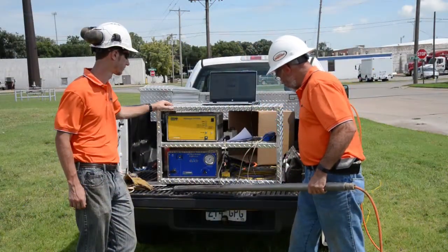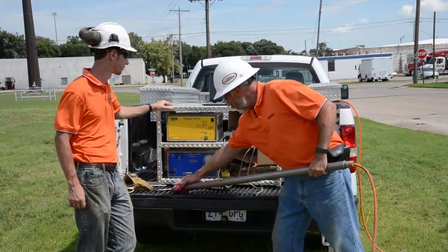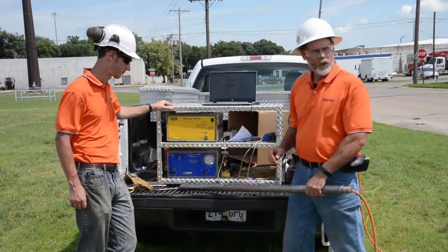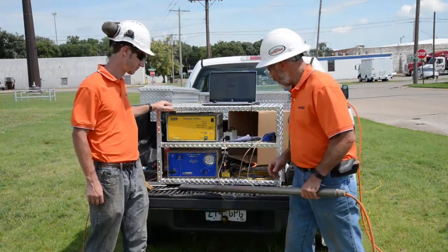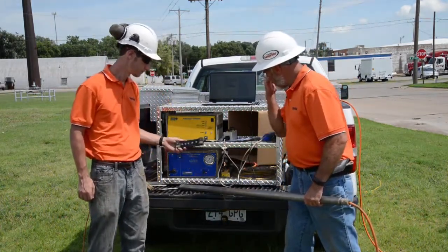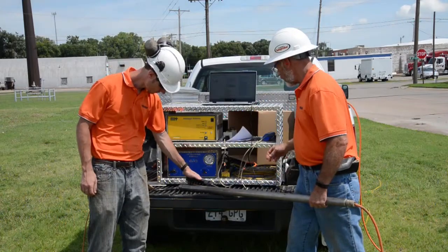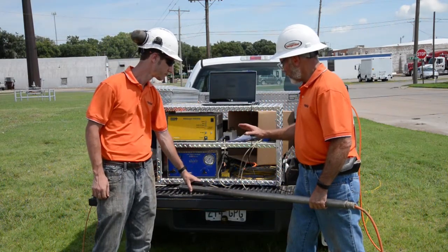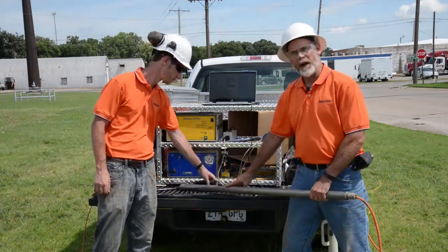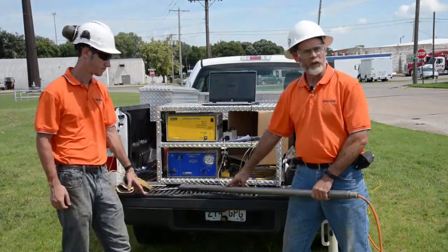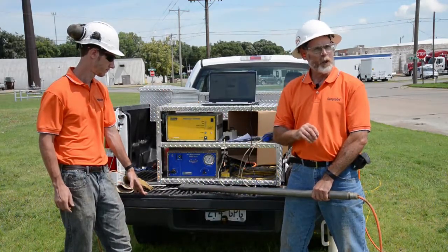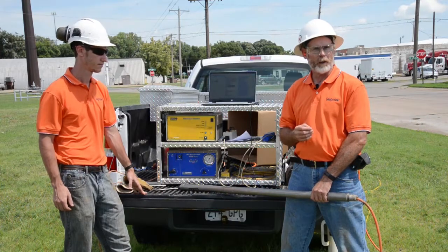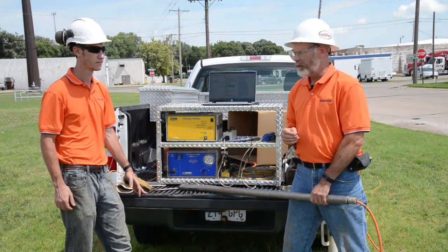Okay, so now we've got the probe out of the ground and we've wiped the worst of the mud off of it. So we're ready to do our post-log quality assurance testing. So first we would do the EC test with our test jig and test load here. And so in our post-log QA, we'll do the EC first, and then we'll go back through the HPT reference test. We'll turn our flow back on, go in the reference tube, rerun that post-log reference test to verify everything is still working properly when we completed the log.